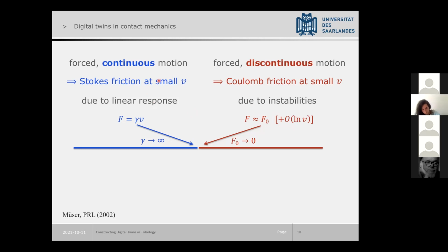So let's assume we keep the size of our atoms fixed and we simply have another counterbody having shorter range adhesion. What happens, like mathematically speaking, there's only continuous and discontinuous. But what happens if you sit precisely at the point between continuous and discontinuous? So on the left, on the blue side, you get a friction law that is linear in velocity and disappears.